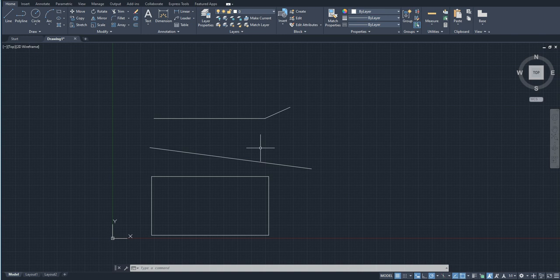Basically that is because you can avoid any confusion while making an AutoCAD drawing. Don't worry, the workspace of AutoCAD is large enough. It can accommodate projects as big as the earth. So of course that's going to be heavy, but let me just tell you that you should just make your drawings in the scale of 1:1.